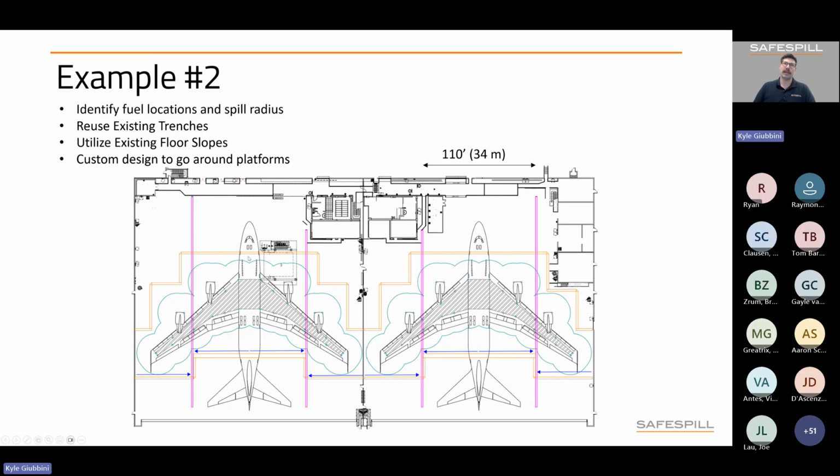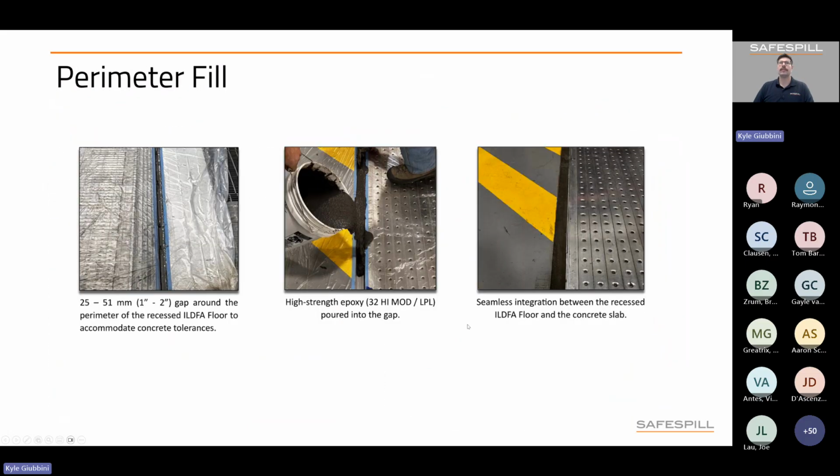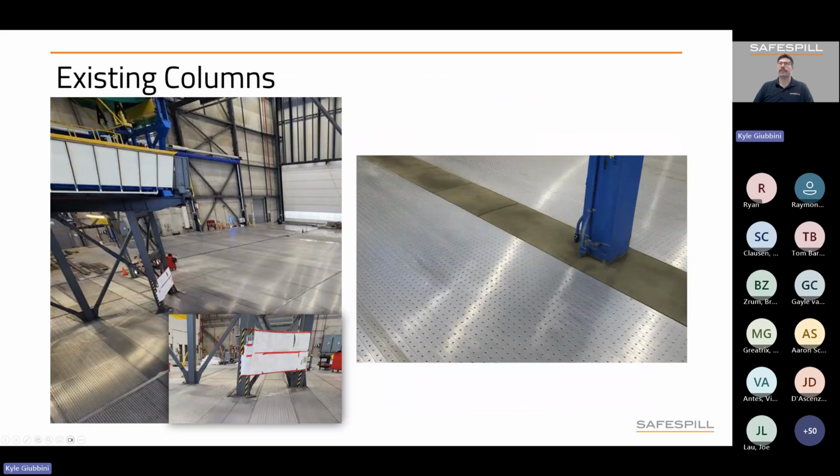So in this application, we do have a high point that runs along the center of this floor. We have floor profiles that run from the trench to that high point, and along that high point, we have a flushing manifold, and we have a cover that anchors down that end of the floor. So there is probably a 4-inch wide space where we don't have the standard floor profile, but rather we have this anchoring element. And there will be some gap between those two pieces that butt up to each other. That's typically filled with that epoxy filling, like we show here. So at the high point, directly underneath the aircraft, we would have an anchoring element that would need a fill between it. So hopefully that answers that question.